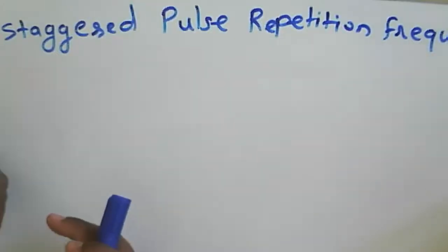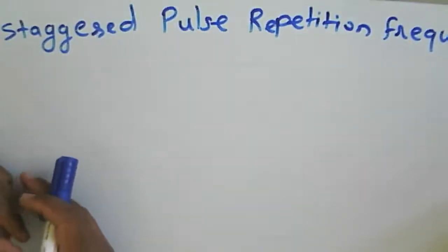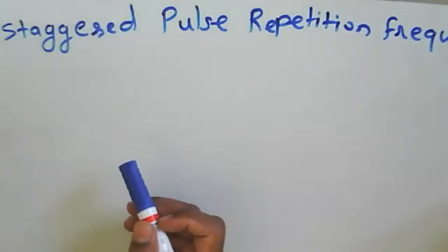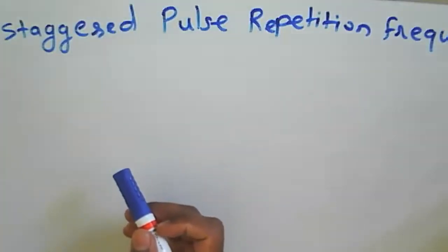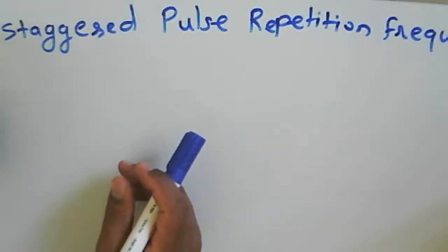We have also seen that a two delay line canceller or a multiple delay line canceller are both useful for rejecting the stationary clutter at zero frequency.